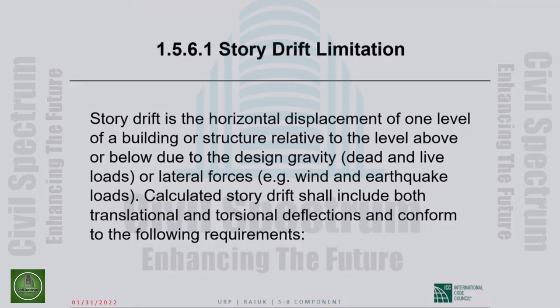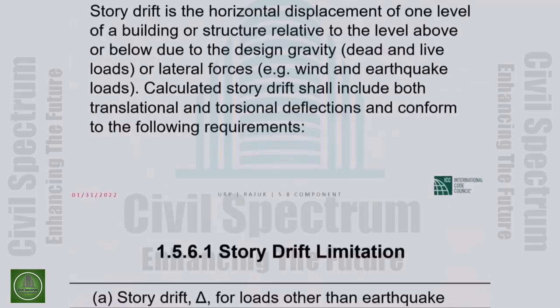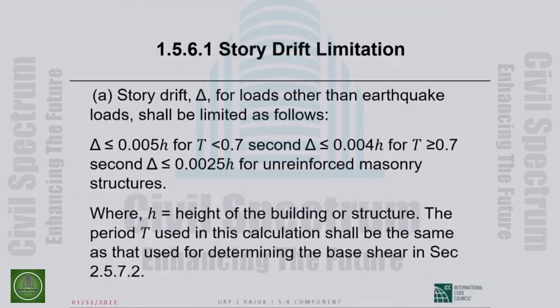The design wind force may act uniformly on the face of your building, or in design, we also consider the possibility that half the face is loaded with full design wind loads, and the upper half of the face is not loaded at all with wind. That will give you quite a bit of torsion, and that may cause drift due to wind. So it is translational and torsional.